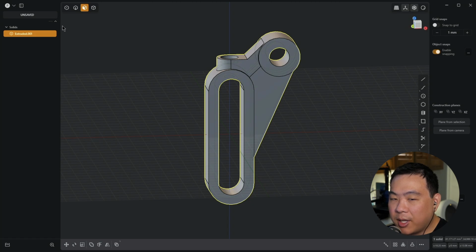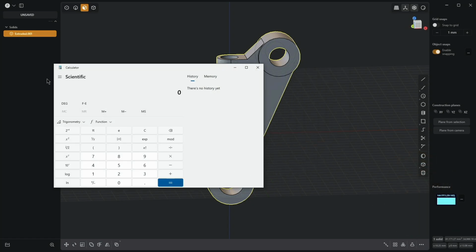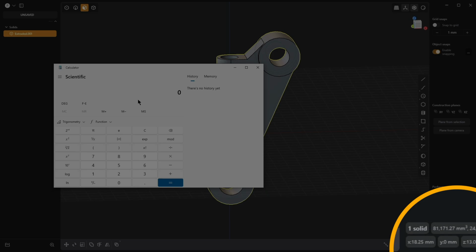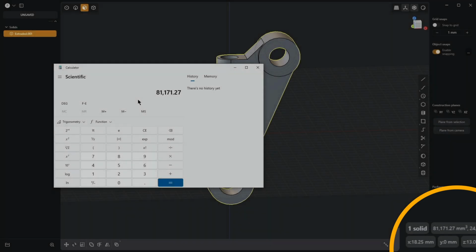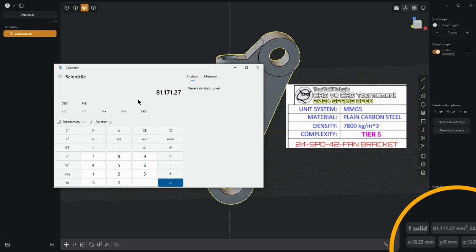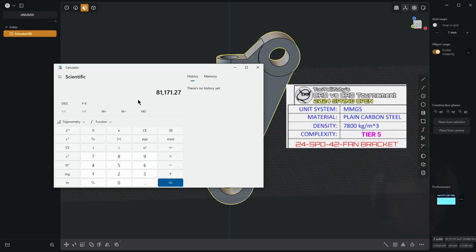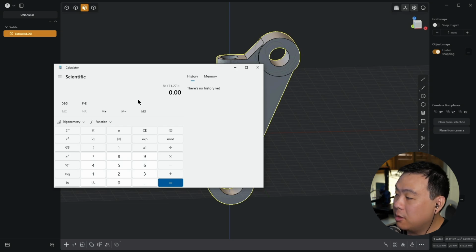Now to calculate the mass, I'm gonna have the solid selected. I'm gonna open up the calculator. And here it says that the volume is 81,171.27 millimeters cubed. And from Tool Tall Toby, the density is 7,800 kilograms per meters cubed. So I'm gonna multiply this by 0.0078. And that gives us our mass of...